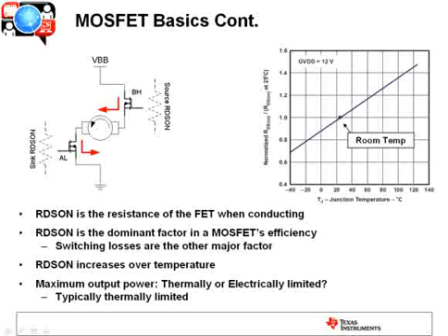So one of the keys to good motor driver design is how do you thermally handle that device? Can you efficiently get the heat out of the device? If you can, you can guarantee you can support the continuous current ratings, and depending upon the device, you may even be able to get higher current ratings out of that device if you can thermally get the heat out of it. That's not the case for every device, but many devices are thermally limited. The challenge is how to get the heat out of it to ensure that you can keep maximum current flowing out of the device.